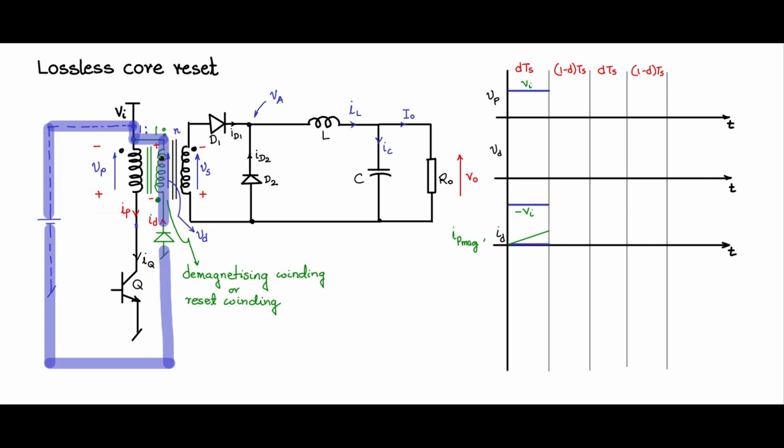So what is the voltage across Vd and Vp? Across Vd, because this is a diode clamping, plus and minus, coming directly across Vi, it will be Vi, measured in this direction, non-dot end positive. In the case of Vp, you will see that it is minus Vi, because this is a 1:1 turns ratio. This is 1:1.